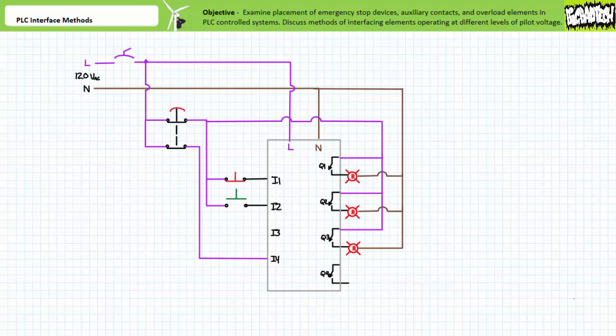If, however, the e-stop is in the activated open condition, the PLC cannot energize any field output device despite repeated attempts to do so. Wired in this fashion, again, the hardwired e-stop directly upstream of all field output devices has effectively severed all outgoing communication from the PLC without the necessity of resorting to any program to do so.